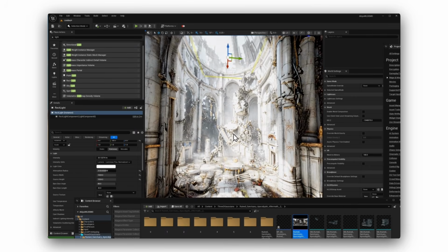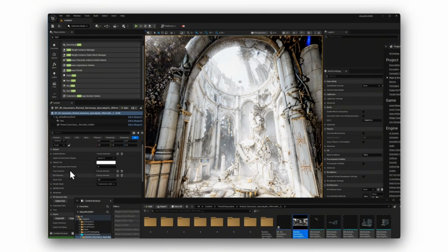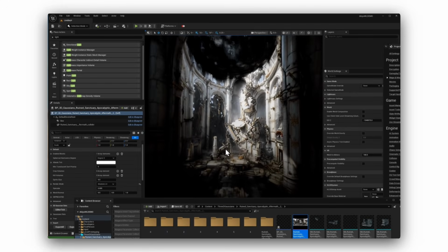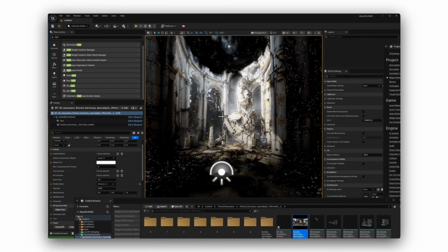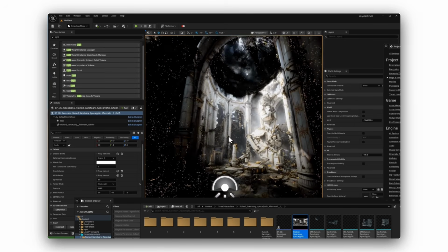And now you're like, cool, but you can't see what's going on. So we're going to select the splat, I'm going to come down to render mode, and right now it's set to translucent unlit. We're going to come down and we're going to change it to masked lit. And as you can see, if I hit G, we start to get lighting in our scene. And we see the speckles because we have the environment selected.